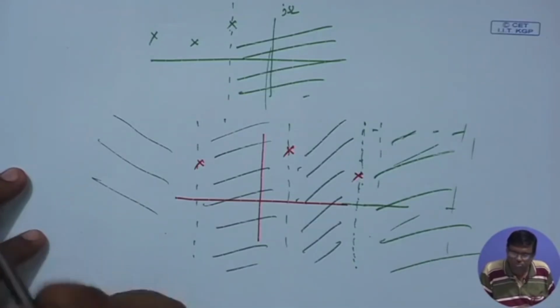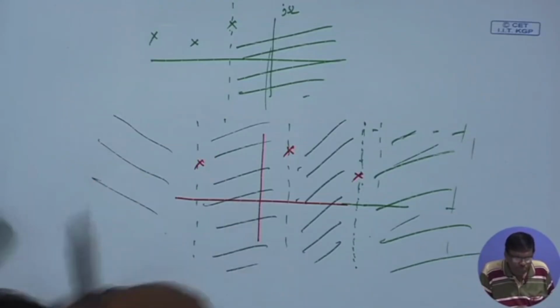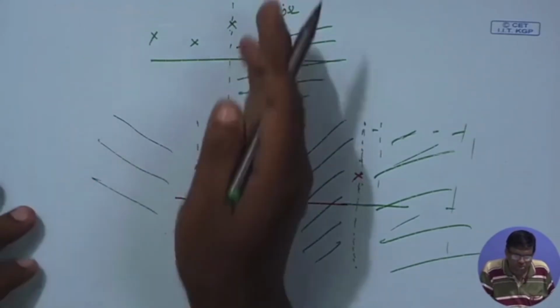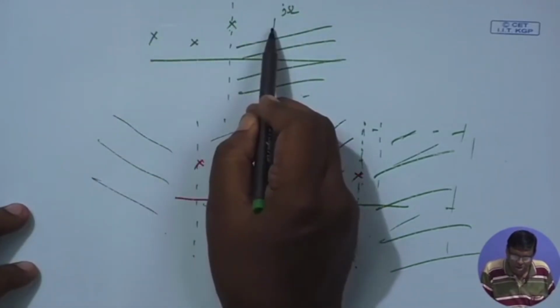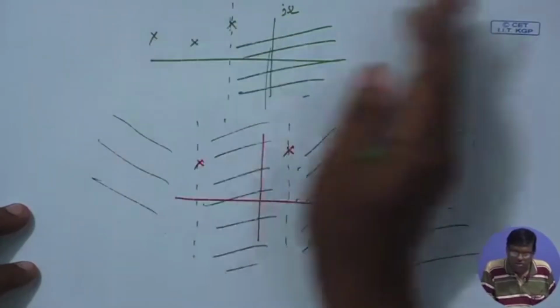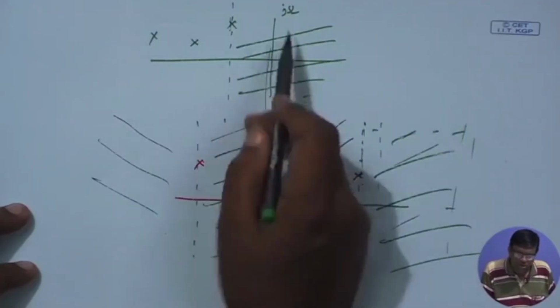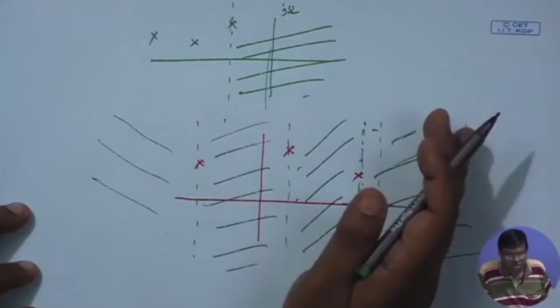So, for a linear and time invariant, causal and stable rational system, all its poles must be on the left half plane. You take the one closest to the j omega axis and draw a vertical line through it, and then go to the right side from that. It will include the j omega axis and go to the right hand side of the vertical line. So, it will be both causal and stable.